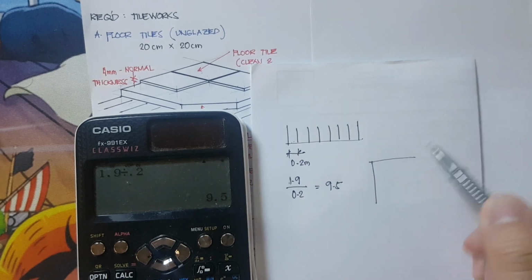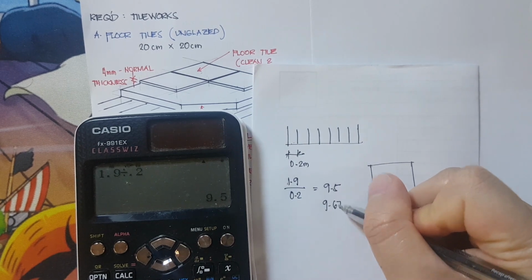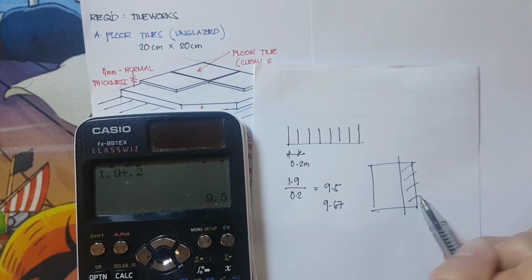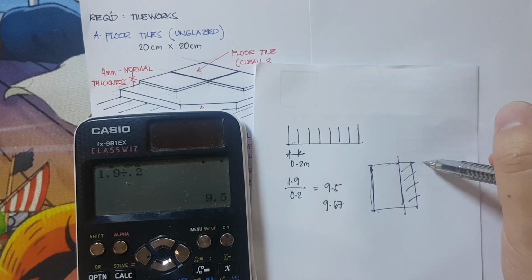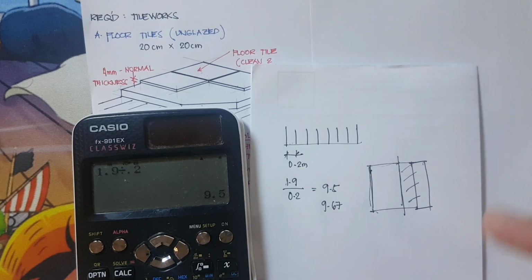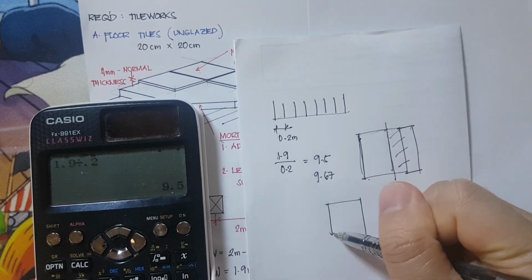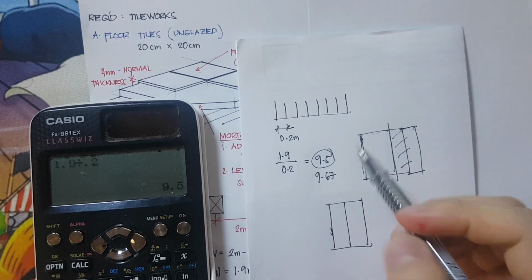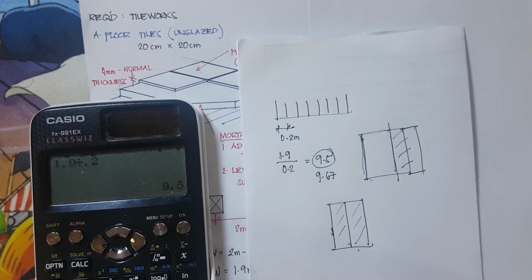Because what will happen is, if this is your tile and the result is, let's say, 9.67, then you will throw away 0.33 of your tile. We need to consider that only usable pieces count, because it looks bad if you put two broken parts side by side. So I repeat, if this is your tile and the result is 9.5, it is okay, because you won't throw away the 0.5, both 0.5s will be used.